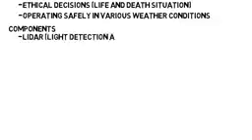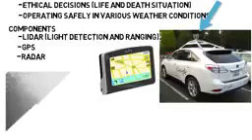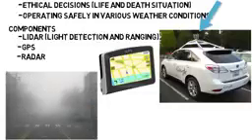Just to name a few, there's the LiDAR, or light detection and ranging, which basically uses light to detect surroundings and is what you see on the top of the Google car here as an example. There's the GPS, which the car uses to navigate to its destination and so that it knows where you are. There's the radar system, which is also used to map out the surroundings, but using lower frequency waves than light, or what the LiDAR uses. And this has its advantages. As one example, LiDAR will not work with heavy fog, whereas radar will.